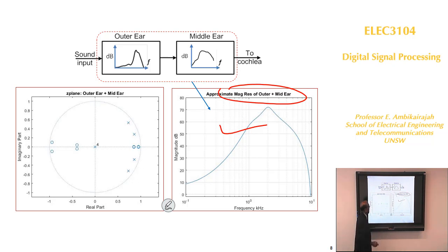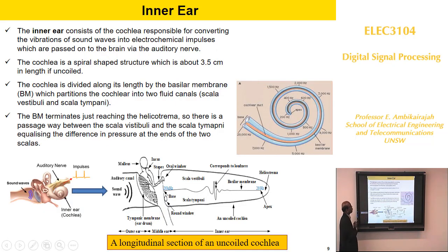These two are combined. Now, you can make variation to it, but don't look at the pole zero here directly. You start to think, if you want a resonance around 3 kilohertz, what you need to do and how you design it, and play around with the pole zero placement in MATLAB to get your filter designed. So I've given you enough details for you to implement this.